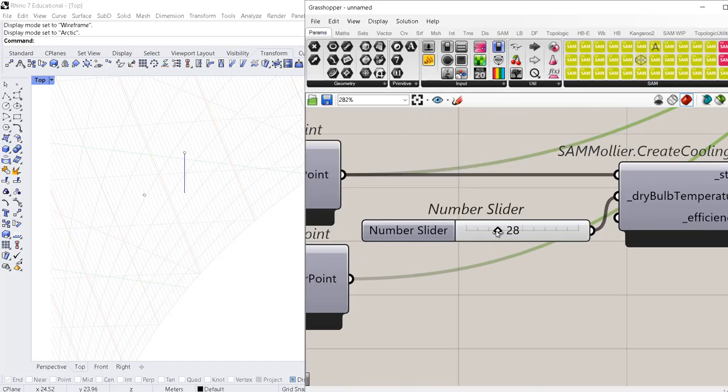So let's go ahead. So now we move along vertically down, down, down, down until we reach the saturation line over here. And when we reach that saturation line, the water starts condensing. And if it starts condensing, that means that the humidity ratio decreases. So now if I keep on moving, you see that it's getting a bit skewed, right? And our goal is to get right underneath this point over here so that later we can simply create a heating process and just by changing the temperature again, rise up vertically over to this point again.